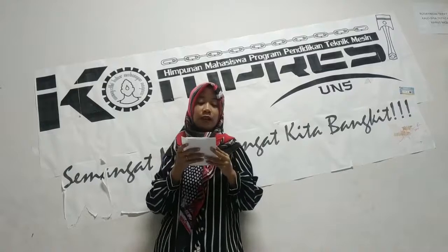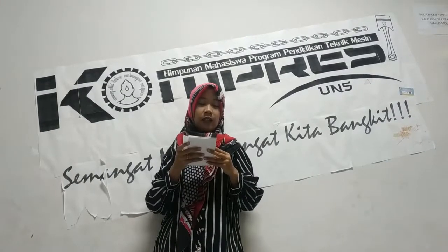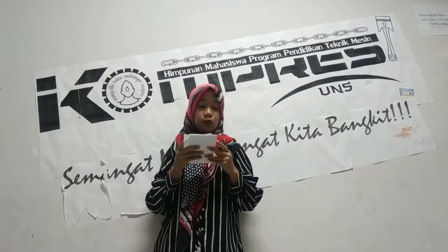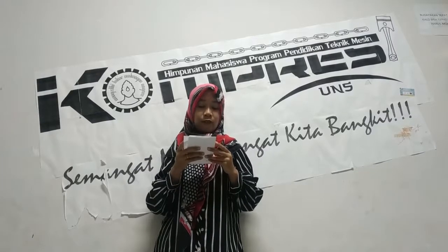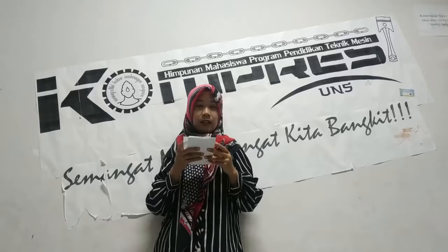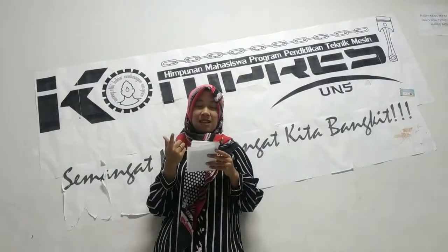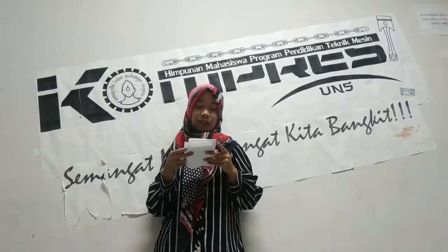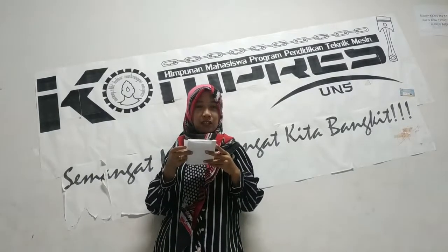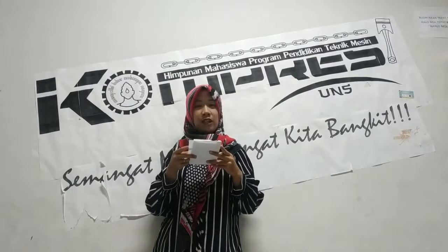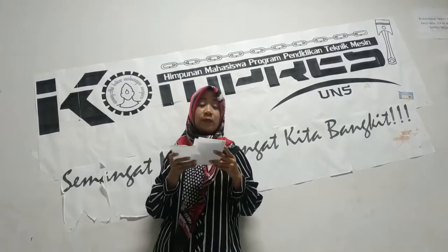First, strategy facing. Second, roughing. Third, finishing. Fourth, grooving. 5, thread. 6, drill. Spot drill diameter 6, drill diameter 6, drill diameter 15. 7, roughing inner. 8, finishing inner. 9, grooving inner, and cut off.